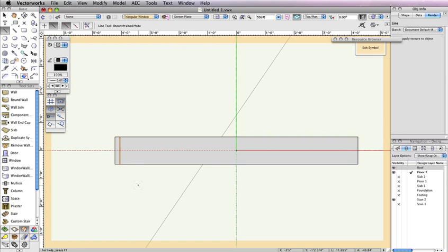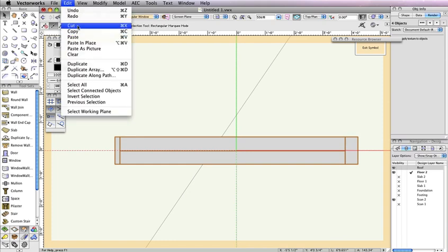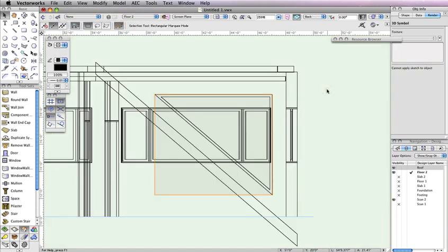create the line. Do the same with the Line tool from the right edge of the frame. Lastly, draw a line from the midpoint of the line on the left to the midpoint of the line on the right. Hold the Shift key and select the three lines and the rectangle you just drew. Then go to Edit, Cut. Click the Exit Symbol button in the top right to return to the drawing area.